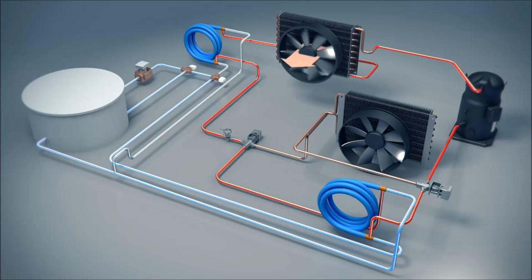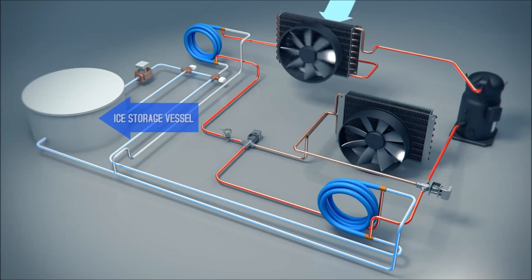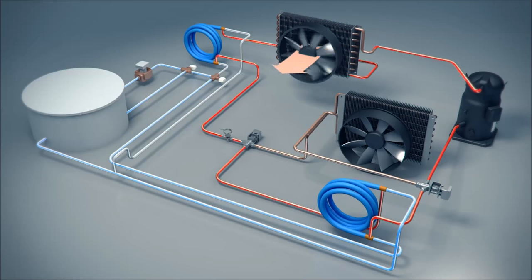The glycol heat transfer medium exits the heat exchanger at a temperature conducive to ice formation at the ice storage vessel. The glycol, at an elevated temperature, exits the ice storage vessel and is routed through a series of hydronic control valves managed by the System Logic controller. The valves function to provide both volume control and loop selection.